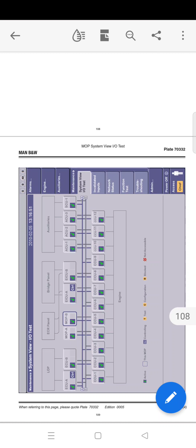So the MPC is also equipped with a light diode capable of showing green, yellow or red light. I will tell you the significance of these lights. This light tells the engineer in what status the MPC is. During normal running, the diode is green. Suppose it is green, there is no need to be worried, it is alright.